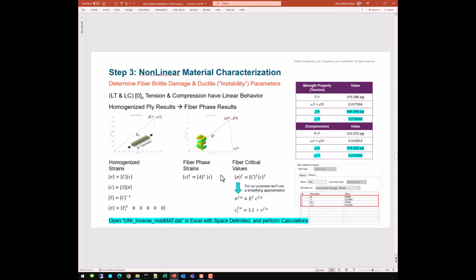We're performing a few different calculations, and what we're really doing is performing the calculations as if I had a micro strain gauge in that specimen, which I don't. But we're amplifying these results, the homogenized results, which is what the ASTM and ISO standards talk about, not the micro results, which is what we're trying to get. So we're amplifying those results. We're just post-processing them through the multiscale material model, which is exactly what the plugin is doing in full 3D and in any finite element model.